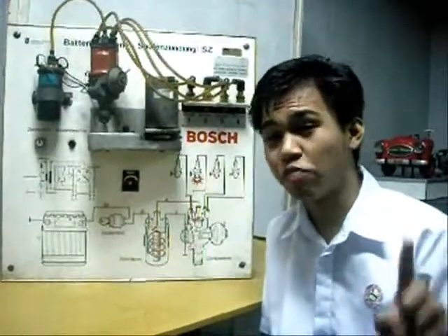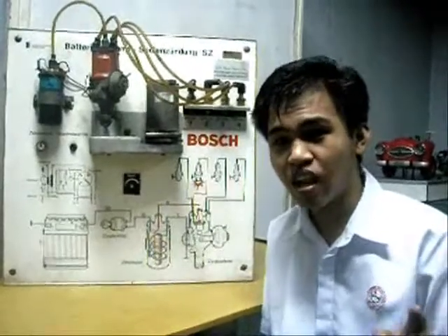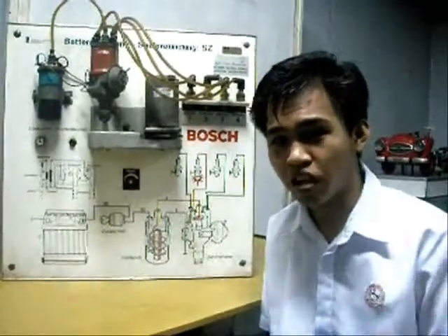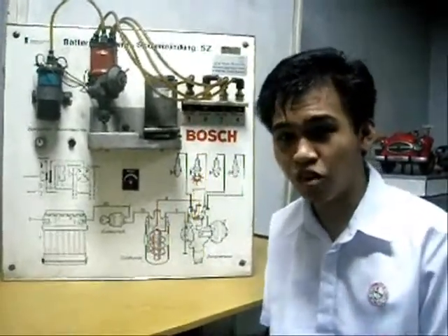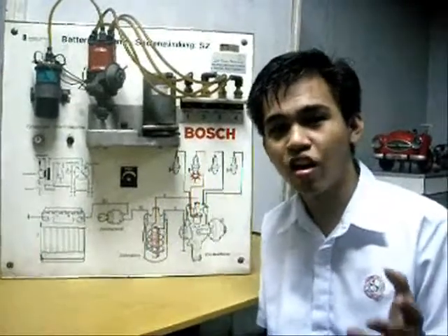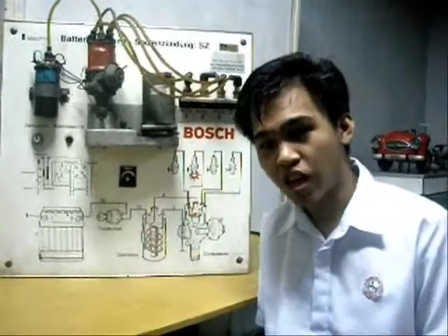The first function of the ignition system is it must control the spark plug and the timing of the spark plug to match varying engine requirements. The second one is it must increase battery voltage to a point where it will overcome the resistance offered by the spark plug.